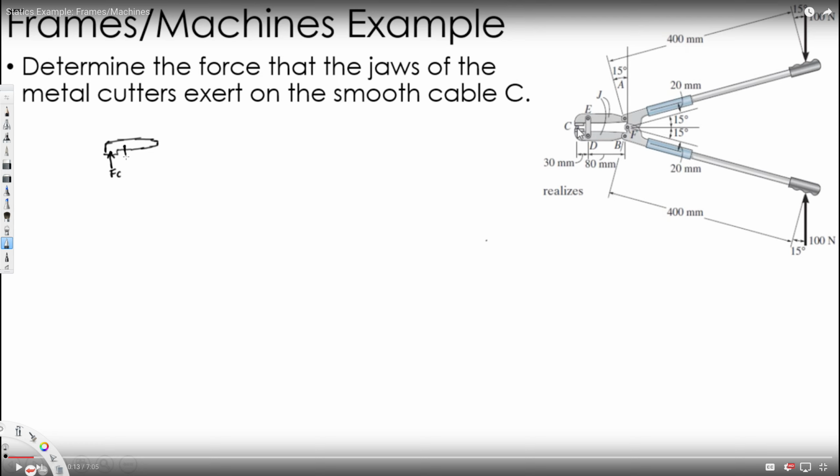And here we have an FV, let's say FED, and also we have A right here, so it's going to be AX and AY. AX is going to be somewhere like this. We don't know the direction, we can just assume, and we will figure it out. First of all, from this one, we can say that Ax is going to be equal to 0 because this is the only horizontal force right here. If I take total horizontal force equal to 0 and solve, Ax is going to be equal to 0. So we have three unknowns.